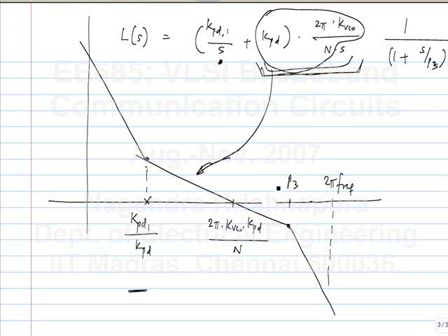So you can have more poles, but they may not help because they have to be between the unity gain frequency and this. They should not affect the phase of the function at the unity gain frequency too much, but they should provide a lot of magnitude attenuation at omega ref, okay? So you can have 1 or 2 additional poles and that will give you a lot of attenuation and you're home free, right?